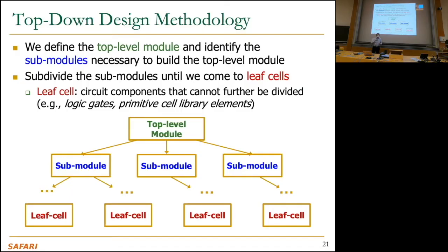Your goal may be to design into some library, let's say. This is a library of hardware modules that you want to use in your design. And somebody creates a nice library, for example, a nice multiplexer, a nice cache, and basically says, this is my lowest level module, leaf cell. A nice cache is my leaf cell. A nice multiplexer is my leaf cell. And maybe AND or NOT gates also exist over there. And your goal is to basically express the submodules hierarchically, and in the end, in terms of leaf cells.